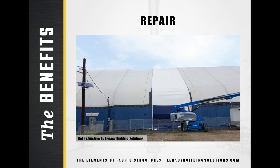In industrial applications, the give of the fabric provides some protection from collision. When the fabric is damaged, it's easy to repair by the building owner or by trained crews. Heat welding or simply patching will restore the fabric to nearly 100% of its original strength. Most repairs are completed quickly to minimize downtime and return to working order as soon as possible. Of course, all buildings are vulnerable to damage, whether from collision with heavy equipment, fire, or extreme weather conditions. Fabric structures using separate fabric panels ensure that in the unlikely event a section of the fabric is damaged, only the damaged area needs to be replaced.